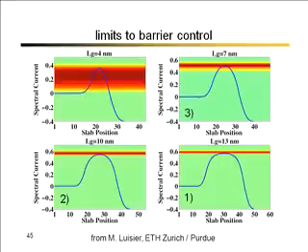If you go to 7 nanometers, you begin to push the model. You can start to see some current going underneath the barrier. Actually, it's not too bad. You can still get by. But boy, when you go lower it really gets severe. If you go to 4 nanometers, the electrons don't even know that there's a barrier there. Now it's really difficult to make a transistor, because a transistor is all about manipulating current by manipulating energy barriers. If the electrons don't know there's an energy barrier there, it's really hard to make a good transistor.